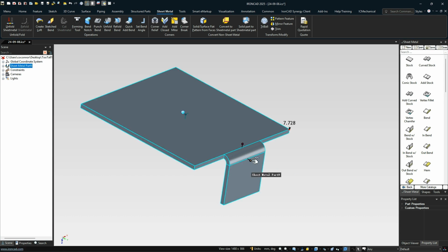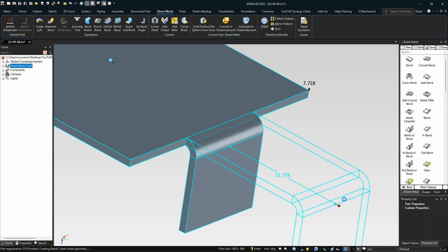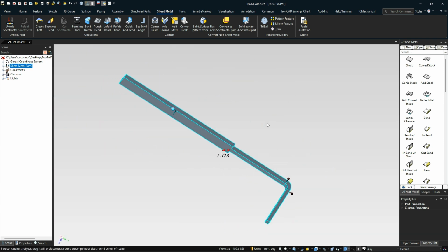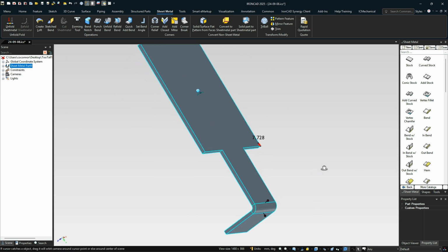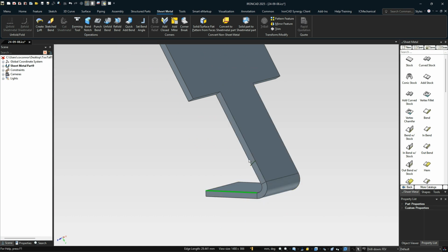We also have what we call part handles. So there's 2 handles here, one for the angle and one for the length. This appears on any bend that's on the part level, which you can actually pull out and add material to your bend, which is kind of nice because that's what we're going to use to drive that distance. So before we do that, let's go ahead and set our angle. So we'll go back to our feature, right click on this and select our angle. In this case, it needs to be 119 because that will give us a total value of 61 there.